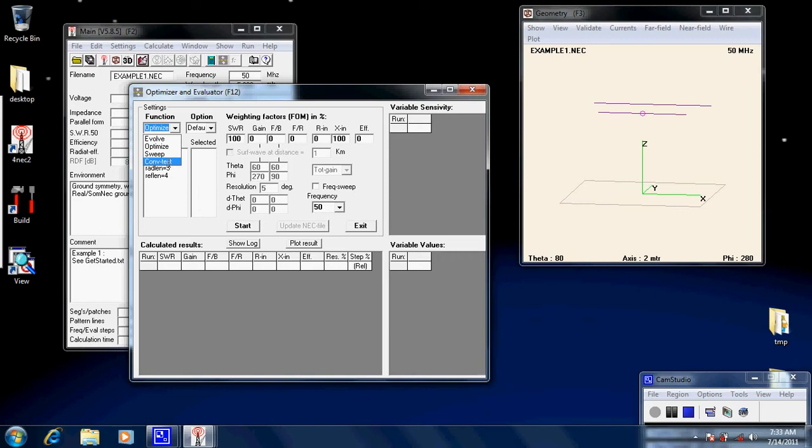It changes the number of segments and a few other factors if necessary, and it basically says, okay, if I change all these things, will the gain and the other parameters which I produce as a program converge to a point? Now the point of that is basically, is the antenna a stable design? So that's the reason. You probably won't use that very often. I don't use it, but anyway, it's there if you do need it. So basically it's to test the fragility or stability of your antenna design.